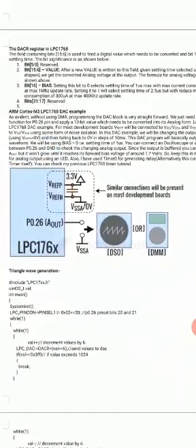So you have the LPC 1768 board here, and the output pin is AOUT, which is P0.26, and it produces an analog signal that can be seen on the oscilloscope or the multimeter. Then you have two reference pins, P and N. As I said, V reference P is connected to 3.3 volt, the VCC, and V reference N is connected to the ground.